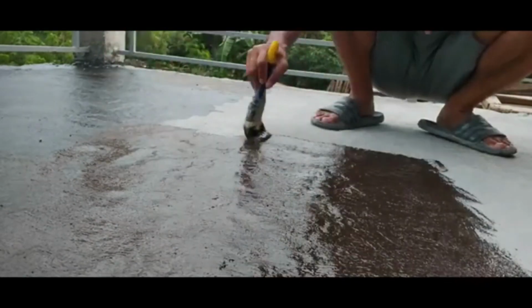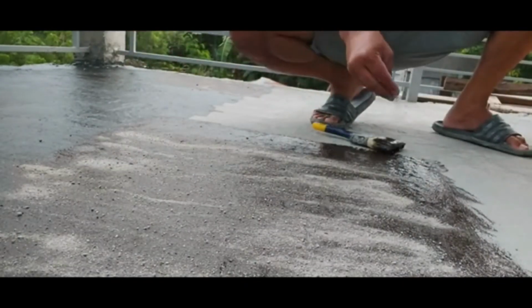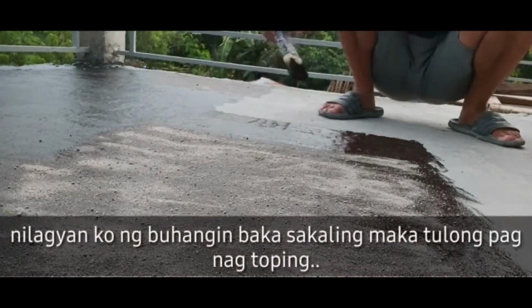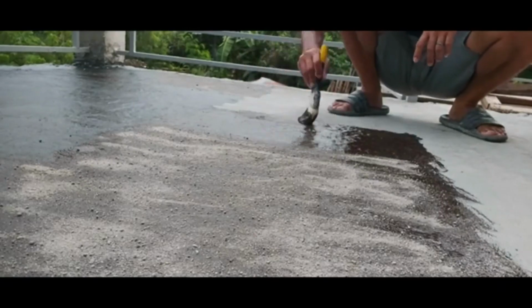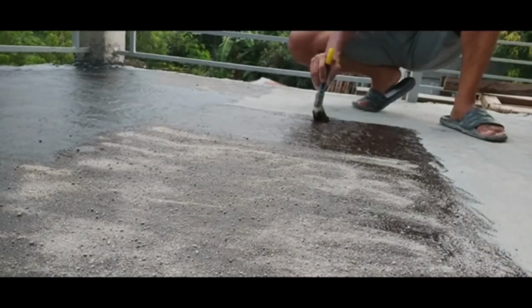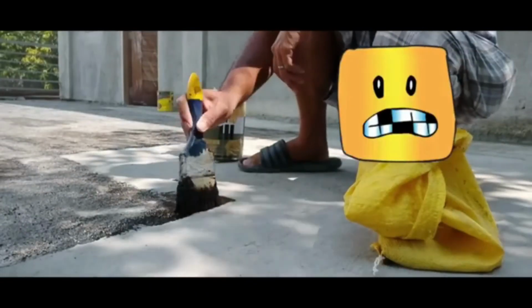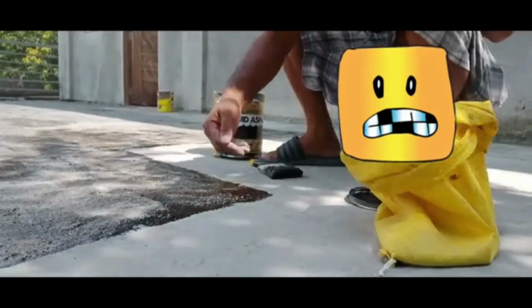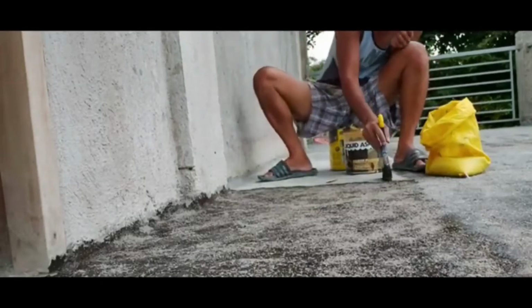If a very durable or strong waterproofing is needed, the workers put on alternate layers of asphalt and asphalt-saturated paper to build up a thick coating on the concrete surface. If the surface of the concrete will not be in contact with moisture and will be exposed to view, like the surface of the piers which support an elevated highway, it is treated in a different way. The workman may treat the surface with a stone finish, a sack-rubbed finish, or a special coating.